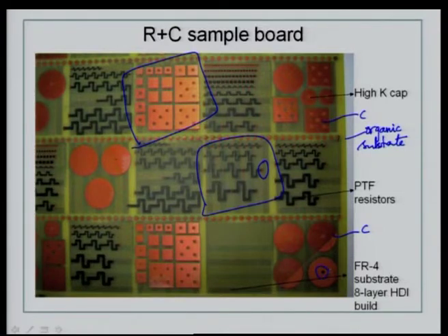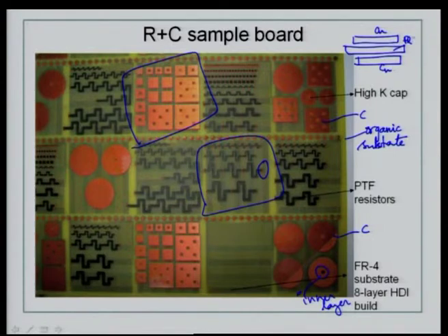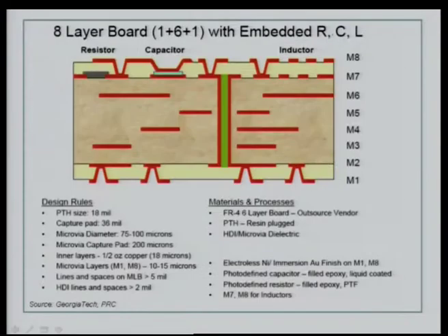And typically in a capacitor what you will see at the center is a micro via interconnect that goes to inner layer, and you can typically measure capacitances between layers. So, if you look at the cross section, you could have copper, then you could have a dielectric and then another copper layer. So, this is a sandwich of copper and the FR4, and then you could interconnect them by vias, and this could be your capacitor. So, you could measure the capacitance of these kind of structures by varying the dielectric material, by varying the thickness of copper, the dielectrics and so on.